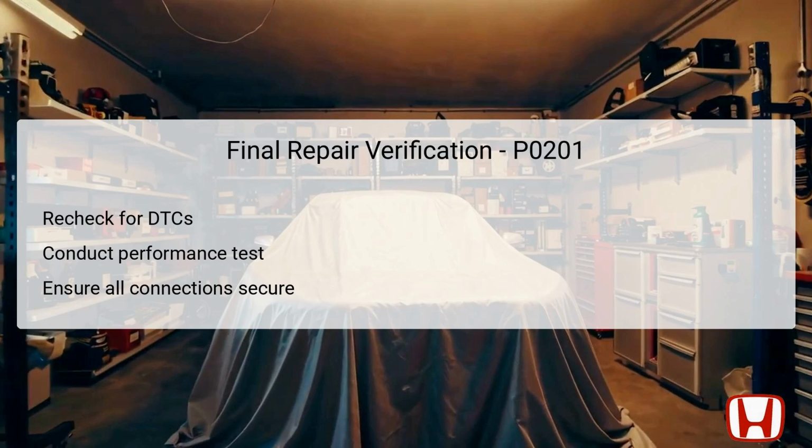Additionally, perform a performance test on the engine to verify that it runs smoothly and without stalling or misfiring, which previous symptoms indicated might have been present. Make sure to double-check that all connections, especially those involving the PCM and injectors, are secure and have no moisture or corrosion. This verification step is vital, as it confirms the repair's effectiveness and assures that no additional problems persist within the injector circuit.